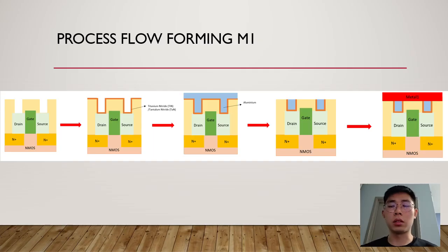We use titanium nitride because it can provide a barrier material between the silicon and aluminum, particularly for extremely shallow connections, that makes a good contact but doesn't react with the aluminum. This is critical, as a common interaction is that aluminum tends to mix with the silicon at high temperature.